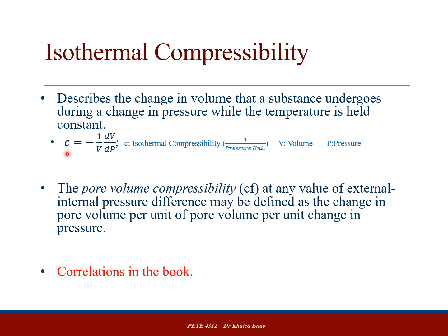So when you start depleting the reservoir, the initial condition, you have the overburden pressure, right, which applies external pressure onto the reservoir. This pressure goes to the grains, and the grains compress your volume. And when you start depleting, you release this pressure, right? So the isothermal compressibility is used to measure or to predict the change in volume based on the release in pressure that goes with the depletion process. Okay.